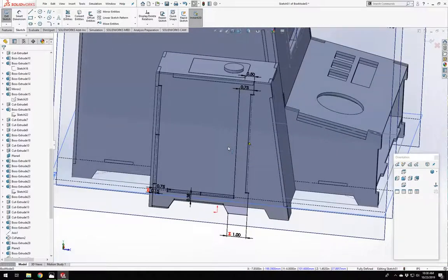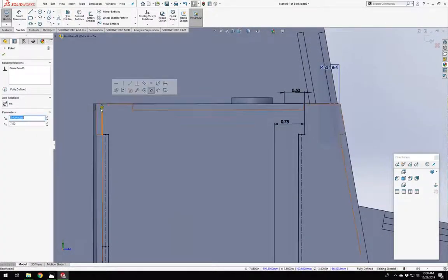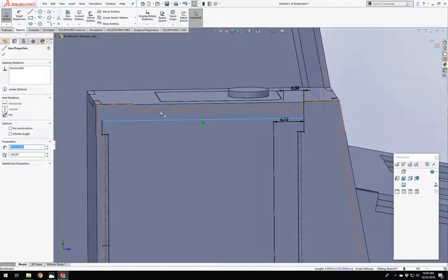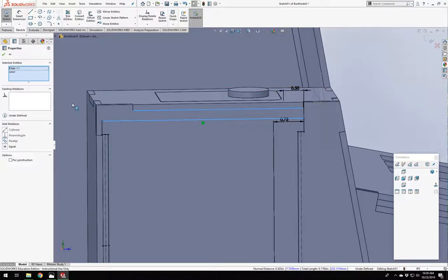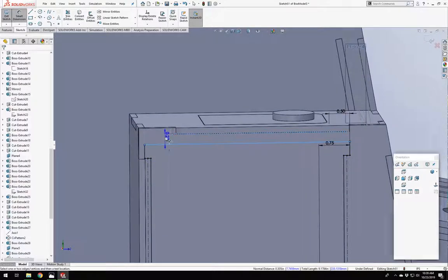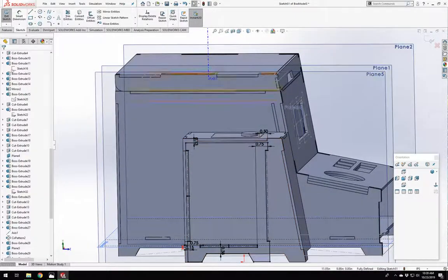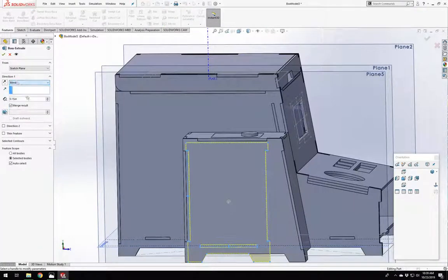And so this is going to be our little box. Oops, it's actually a little too tall. This needs to be below, because we don't want it to be full height. It needs to be against the bottom of that, or probably just so we don't run into any problems, let's have it slightly offset from the bottom of that, so it'll be just a little bit shorter, which will be fine. Great. So we're going to extrude that. Our material thickness again. Don't merge.